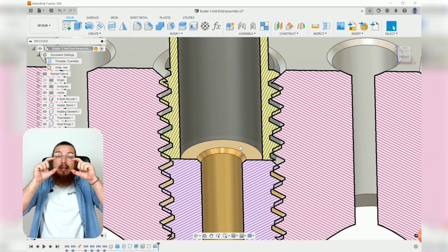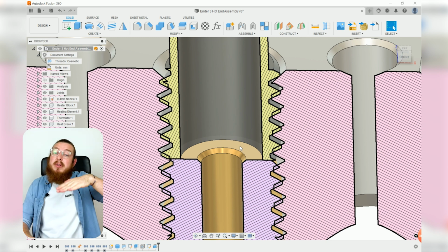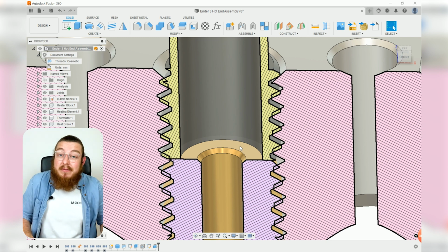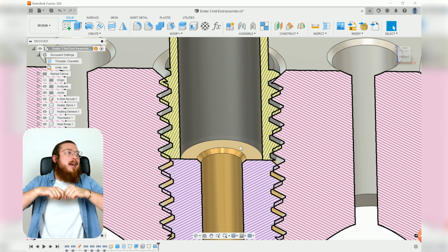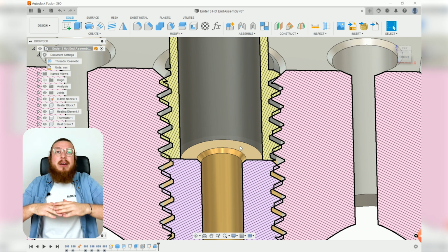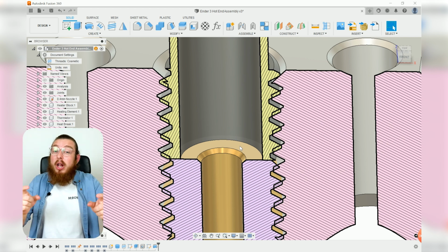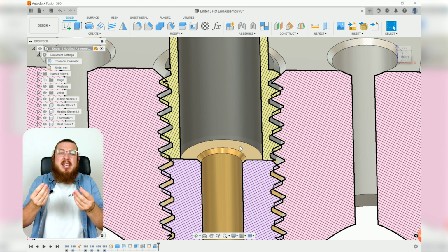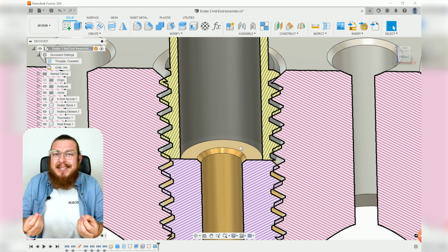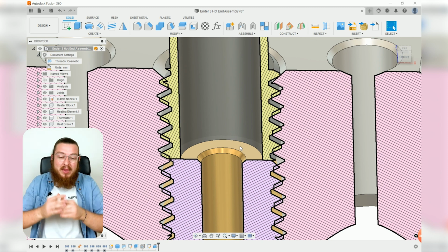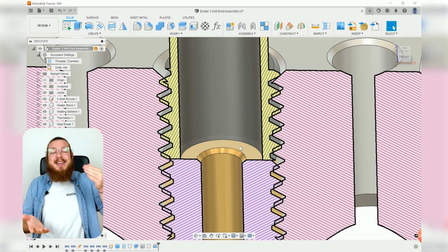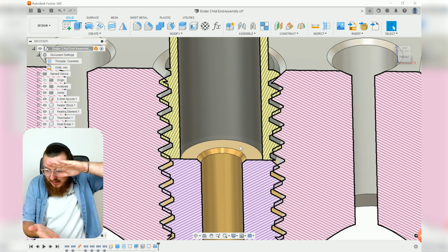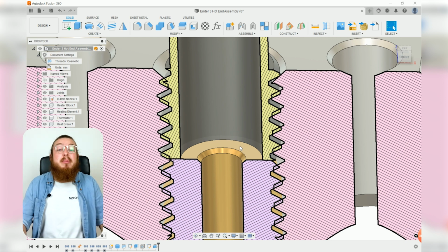If there's even a little bit of gap in between the top of the nozzle and the underside of our PTFE tube, then this is an area where melted plastic can get trapped, and then it will heat up, cool down, heat up, cool down, and it starts to break down from a polymer down to a monomer, which is this really gunky, almost tar-like plastic that just never re-solidifies. As far as maintenance goes, it turns into a nightmare glob mess. So we want to make sure that anytime you have a PTFE tube, it is pushed down all the way onto the top of our nozzle.